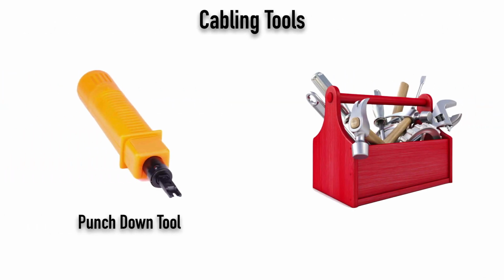If we're putting a wire into a wiring block, like a 110 block they're called, you might use a punch-down tool to make this wire be inserted between 2 little metal blades. And these blades, they cut into the wire just deep enough to make contact. They cut through the insulation and make contact with the inner conductor.